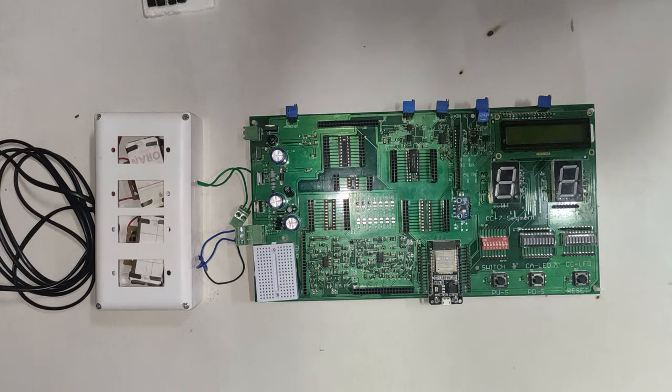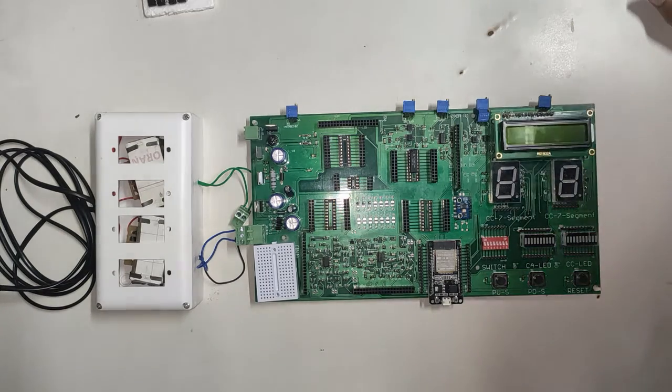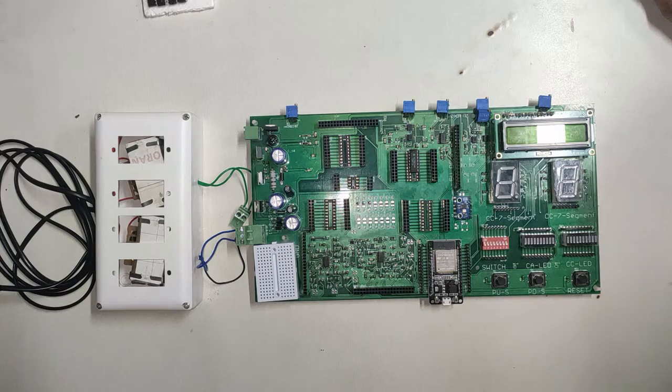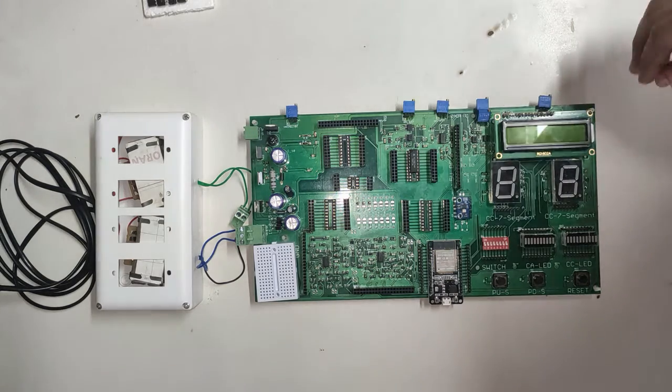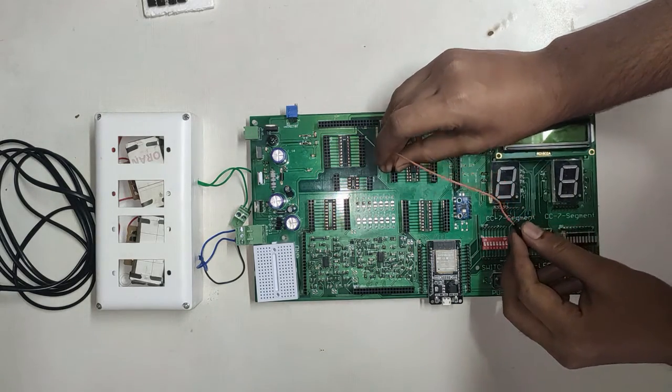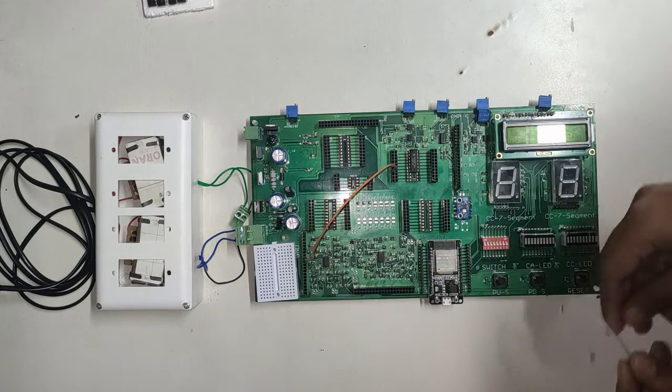In this part, we'll demonstrate how to implement a D flip-flop, that is the IC 7474. To implement the D flip-flop, at first you will have to refer to the pin diagram of IC 7474 given in the manual. Now let us start with the connection. Pin number 7 is ground and pin number 14 is plus VCC.